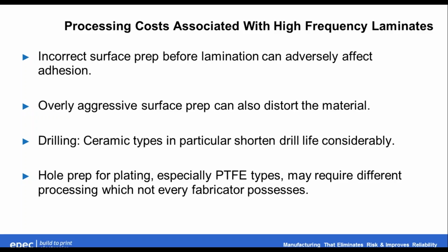Again, you have to remember some of this material is actually Teflon. So you know, Teflon is known for not sticking. That's its most famous property. So you have to be very careful how you surface prep it. The other thing that can happen in surface prep is it can distort. Some of these materials are a little softer than what you're accustomed to with FR4, and they will stretch if you have, say, some rollers that are too close together, they can deform the material.